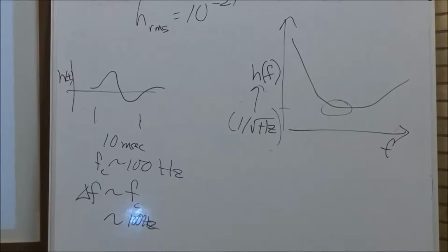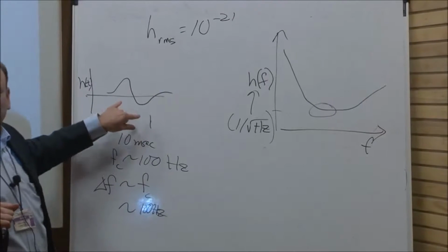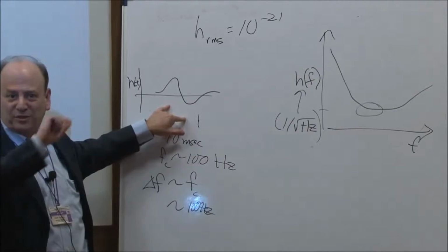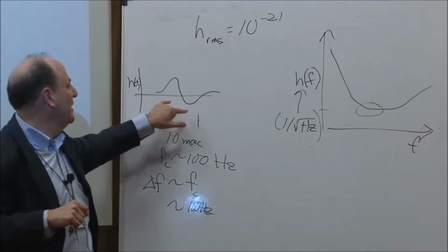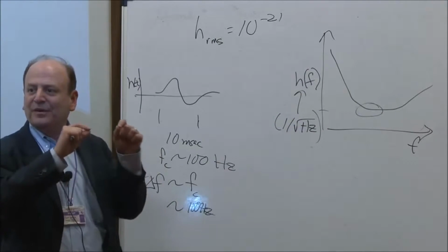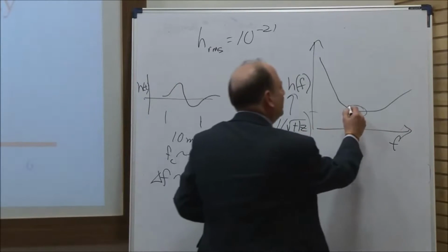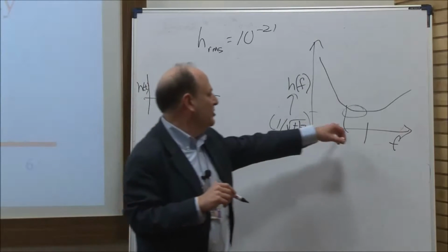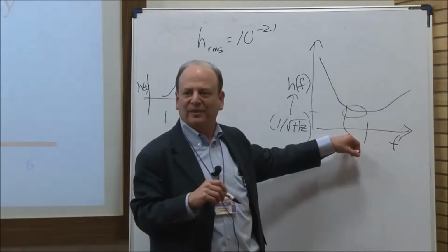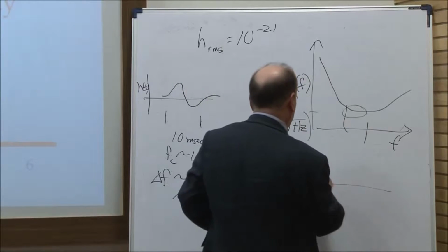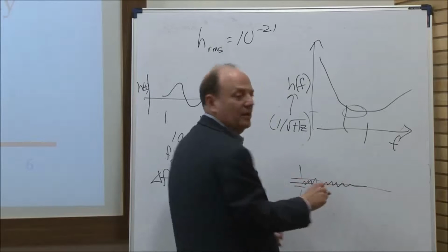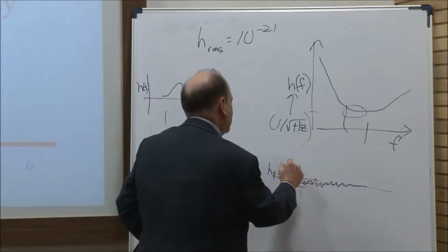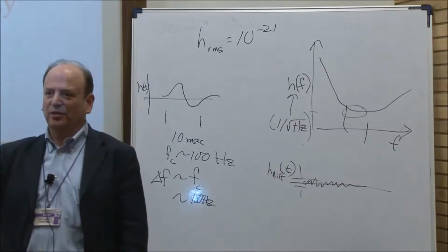So if I make a well-constructed search for this kind of signal, such as the kind of matched template search I described yesterday, doing the cross-correlation between a template and the noisy time series, in spectral language, I'm going to be admitting about 100 hertz's worth of noise, centered more or less around 100 hertz. And it's that noise that's going to contribute to the RMS of the result of the output of my cross-correlation search.